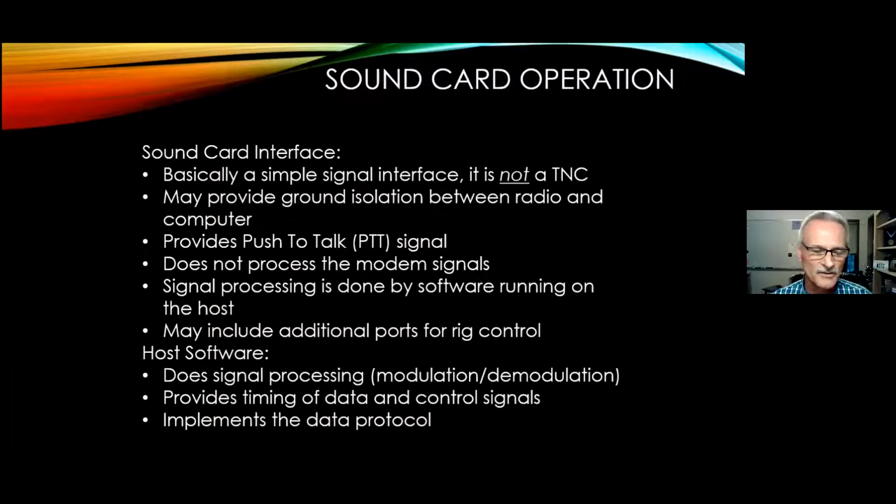So all of the signal processing is going to be done by the software that's running on the host computer. And that software is going to do the modulation and demodulation, essentially. It's going to do the timing and the control signals like push to talk. And of course, it'll implement whatever the data protocol is that we happen to be utilizing.